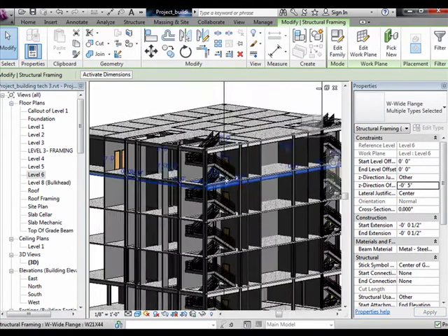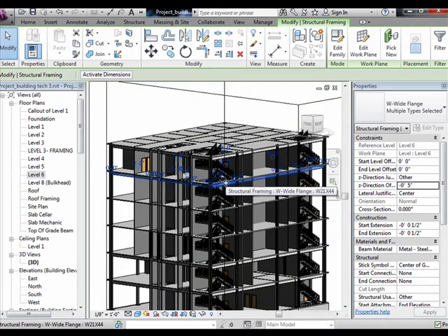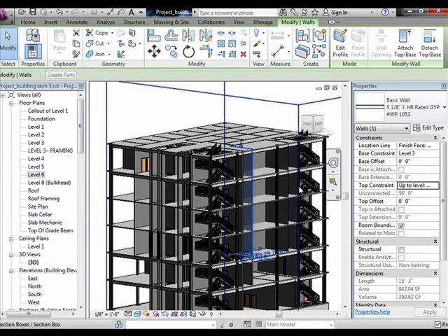When it comes to framing, it is a good lesson to learn to group objects, especially when they're similar from floor to floor. Even partitions. In your case, you could have taken all the partitions here and grouped them in one floor. So what I'm going to do is take all those partitions on the 6th floor, make them from 6th to 5th only.